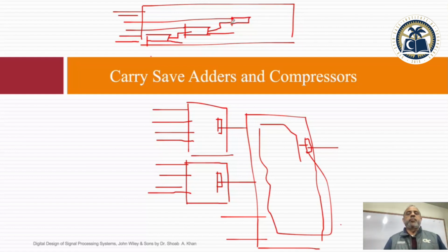So once you're pipelining, you need to find out where you have to pipeline, but you have to put a cut set, which will cut the entire design, because then you are going to hold the rest of the values as well. So all those which are not being processed are to be put in the pipeline register, and that is what is important. Otherwise it will not be a synchronized design. So synchronization means that every cycle you can have new values, and all these pipeline registers would ensure that you will have a throughput of a single cycle.